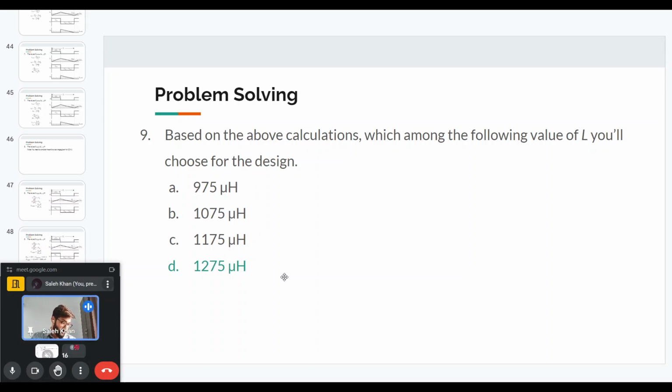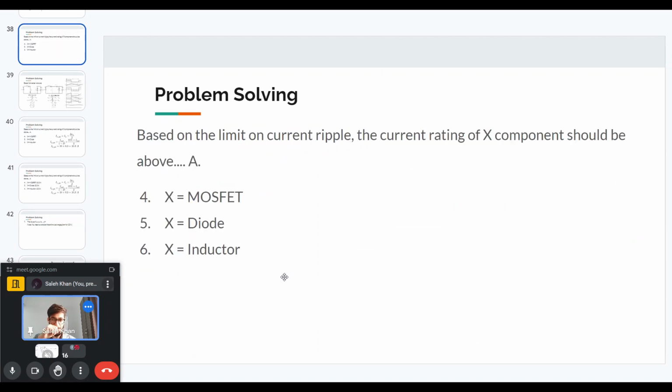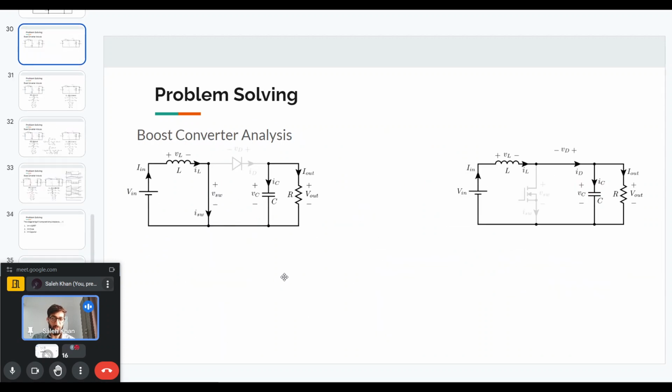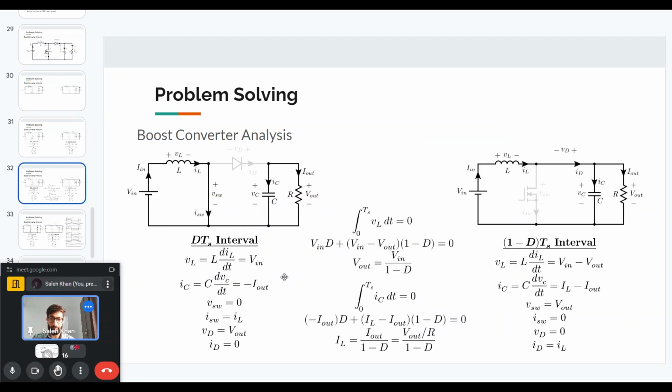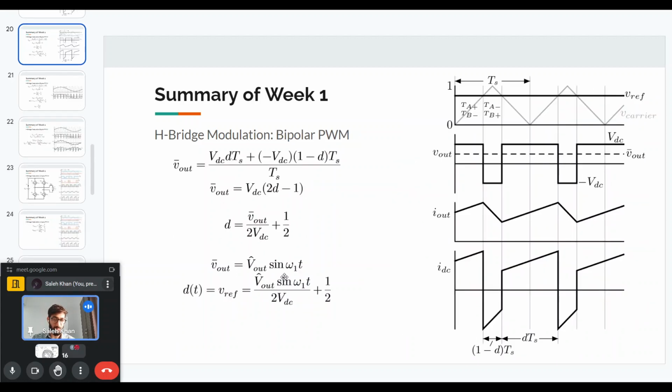Can you explain full bridge without carrier frequency, simple PWM with deadband? Without carrier frequency, yeah, you can give a simple duty to the H-bridge, but it depends on which switches you are turning on of the H-bridge. Based on which switches you are turning on, you can find out the average output, just like here you are finding out. The deadband is actually very small compared to the switching cycle, so it does not affect the output voltages in a major fashion. So while doing the analysis, we actually ignore the deadband.